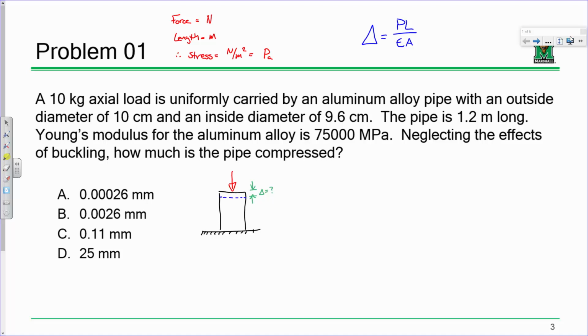But it's all acting along the axis of the member, which is, if you look at these expressions, they're very similar. We have the applied load, the member length, a material property, and a cross-sectional property, okay? That's why those two topics go hand in hand quite well. That's why usually you cover axial loads and then you cover torsion right after, because it might not seem like they're related. Take a member and yank on it, twist it, but the math actually works pretty well.